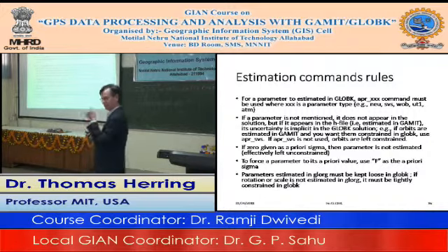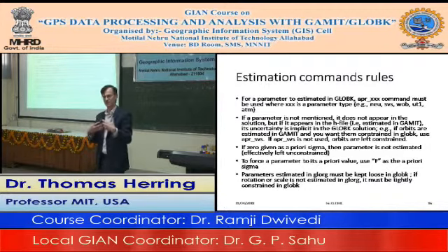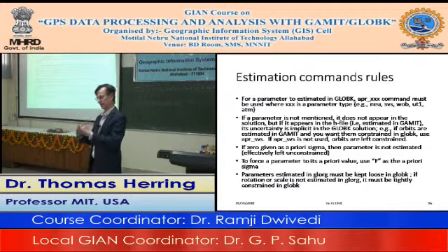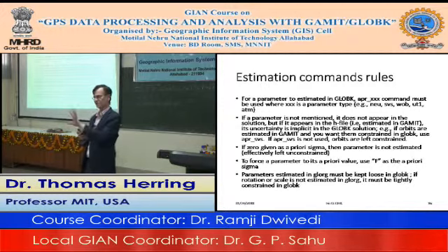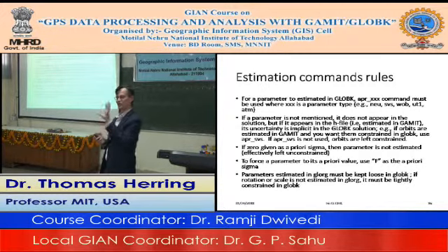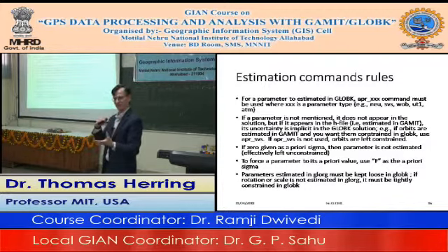translation. Scale in GPS, we heard the other day when we talked about coordinate systems that people often do a seven parameter Helmert transformation with scale. Scale in GPS is not rank deficient if all of the satellite antenna offsets are fixed. And even when they're free, it's still not rank deficient, it's just poorly determined. So scale is one of those cases, again, that in the way the GLOBK algorithms work, you have to explicitly estimate it if you are going to use it in part of your frame realization.